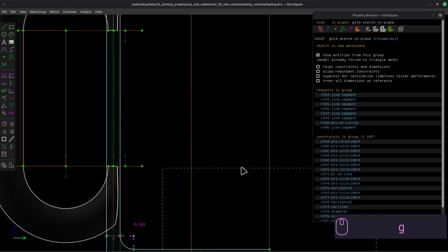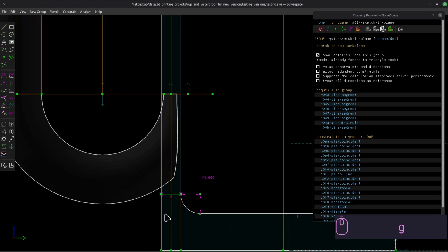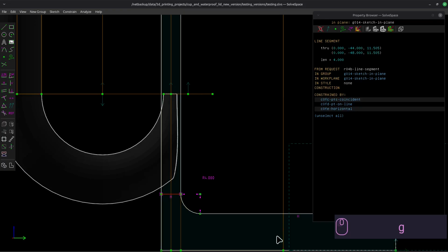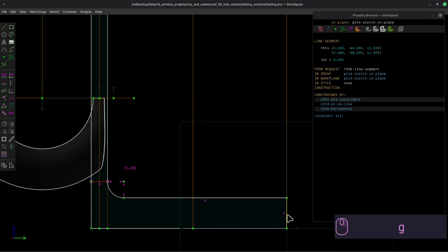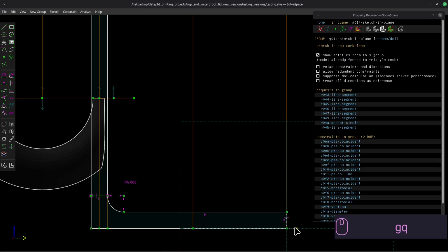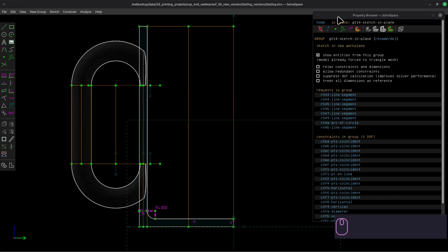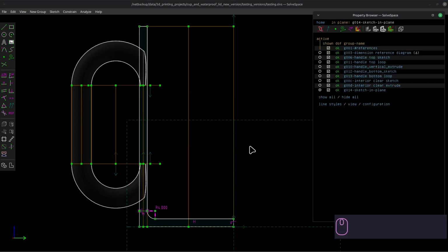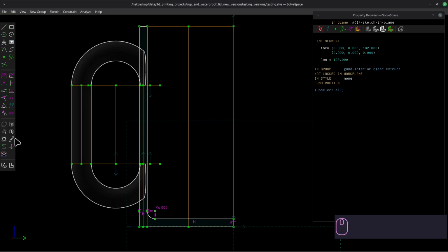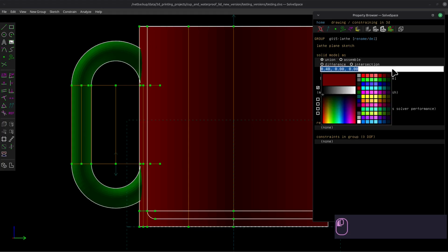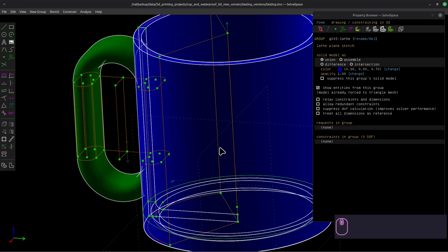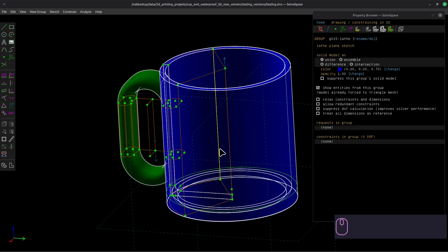To carry the wall radius over so that the floor radius will track it. Q. Now the floor radius, the wall radius will both be 4 millimeters. Okay, looks good. And let's make a body. Okay, that's phase one.